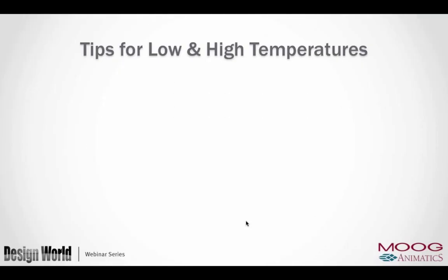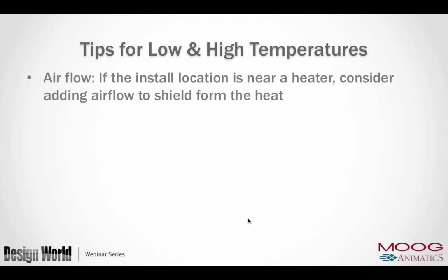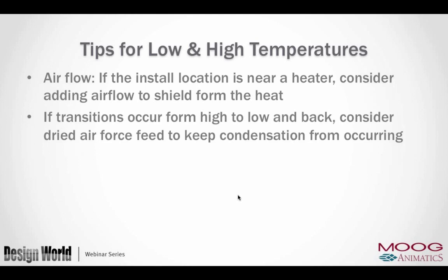We've had multiple people that say, machine ran great during the day, but the next morning it runs horrible. That's because overnight it actually sucked in that moisture and caused problems. Okay? Tips for that, low and high temperatures. Airflow. If you install it in a location near a heater, consider adding airflow to shield from the heat. Okay? If transitions occur from high to low and back, consider dried air forced feed to keep condensation from occurring. In other words, feed it some dry, clean air.